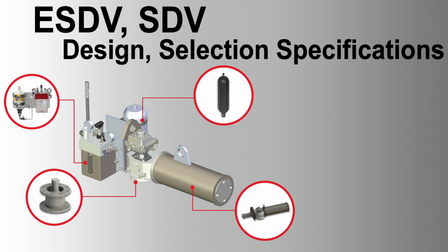Solenoid valves. Type: 3-port changeover spring return type, SS316 body and trim. Operation: normally energized to open, fail close for ESDV; normally energized to close, fail open for BDV. Coil: 24 VDC, insulation class H, weatherproof IP66. Fail-safe design: must provide tight shutoff TSO feature and be certified for hazardous areas.